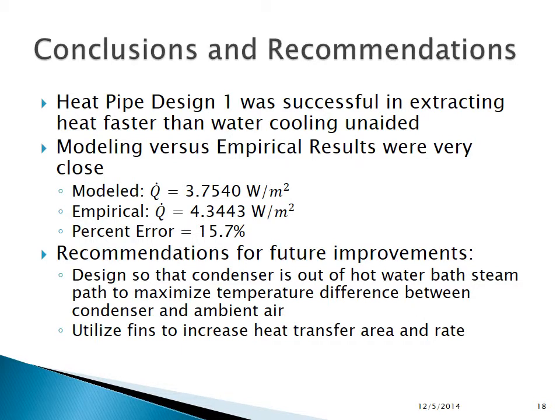The modeled and empirical data were compared, and there was a 15.7% error. Recommendations for future improvements would include modeling the heat pipe so that the condenser is out of the steam path, and to utilize fins to increase the heat transfer rate.